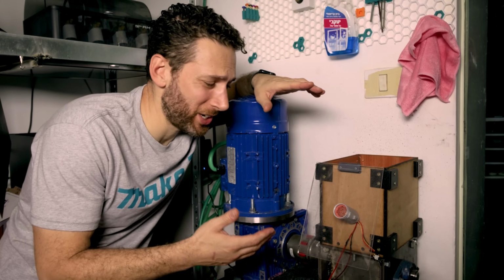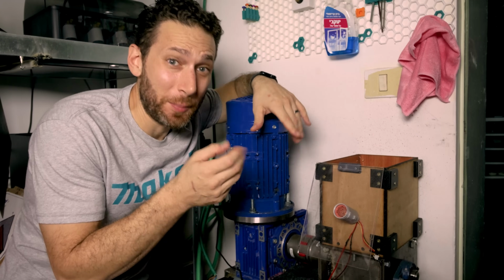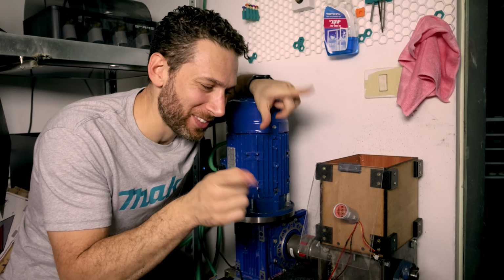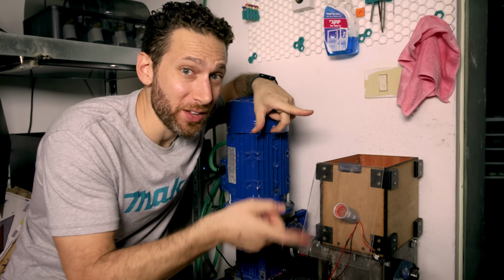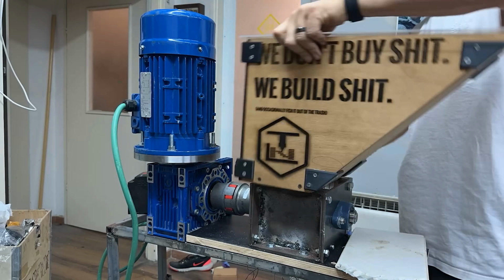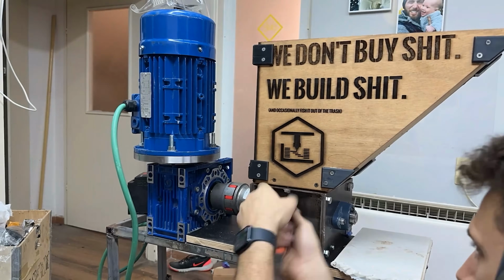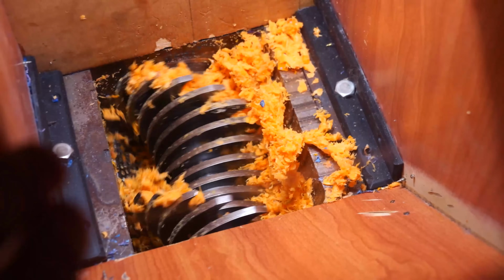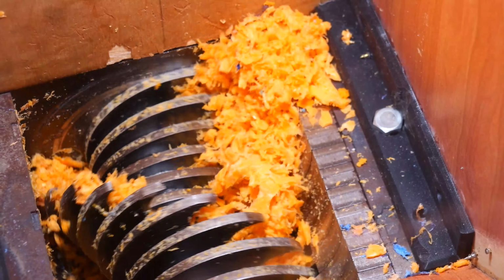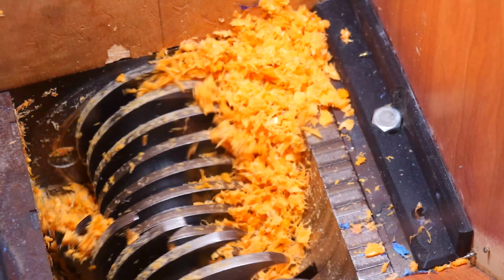But unfortunately, that is far from the biggest problem I actually have with the shredder. The biggest problem I have with the shredder is actually a twofold one, and I do think that the two problems are related. First, the friction on both the plastic on the steel and the steel on itself because of my imperfectly made shredder are causing an insane amount of heat, like melting the PLA into goop levels of heat, which is causing it to not actually push the threads through, but rather churn everything into dough.